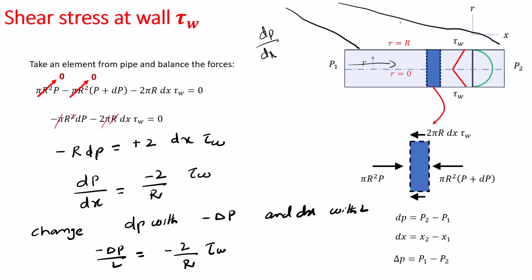Okay, and this linear profile is only true for fully developed flow. If some portion of the pipe has developing flow, then the profile might be different, like this. But once the flow is fully developed, then the profile will be linear, and it is defined by dP by dx. And to make it a minus value, basically what we are doing is making the gradient a positive value.